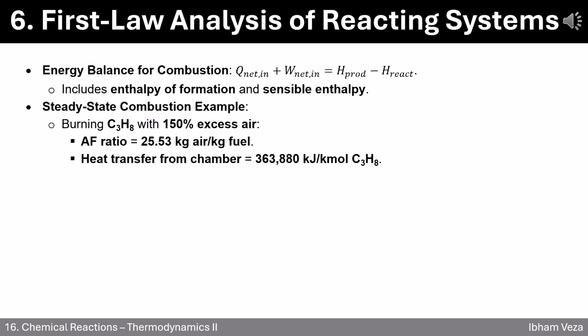6. First law analysis of reacting systems. Let's now apply the first law of thermodynamics to reacting systems, specifically combustion. The energy balance equation states that the heat and work going into the system equals the difference in enthalpy between products and reactants. This accounts for both the enthalpy of formation and the sensible enthalpy due to temperature changes.